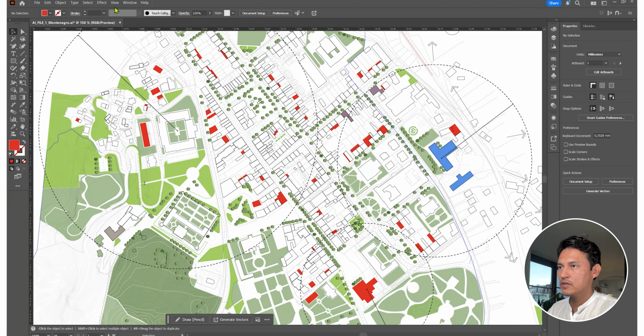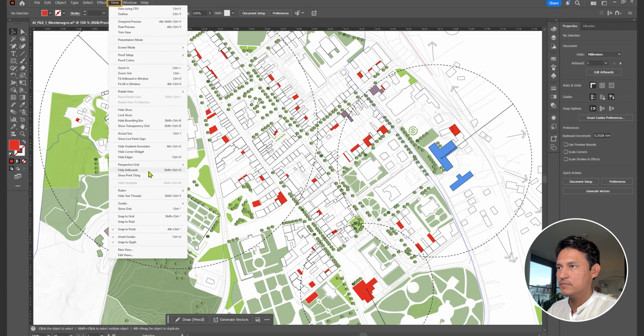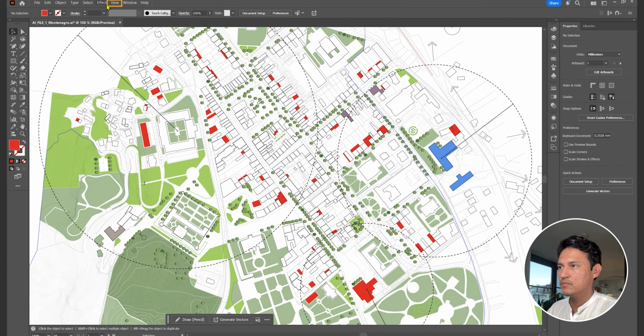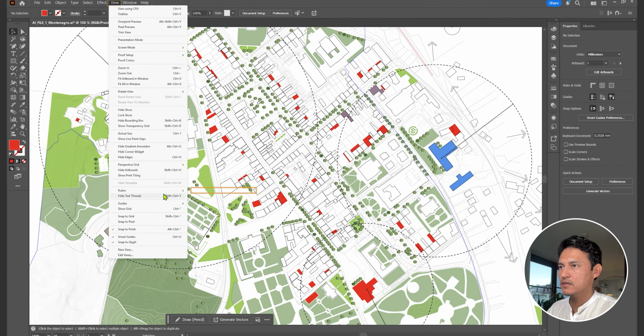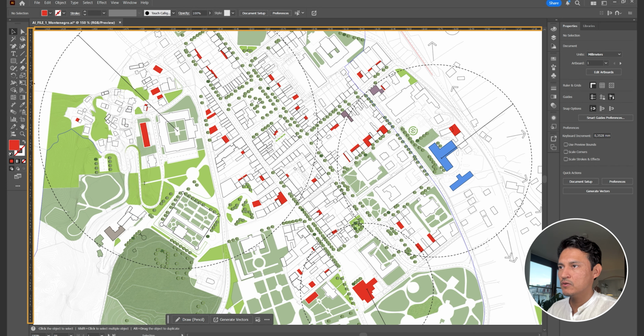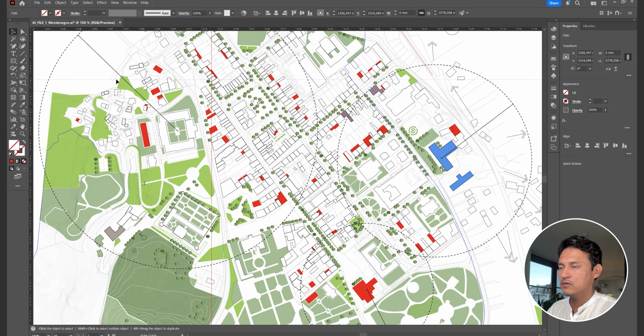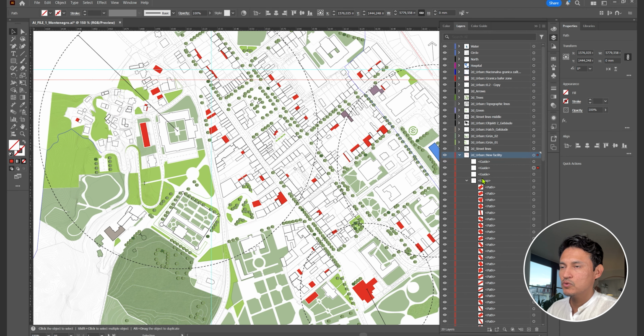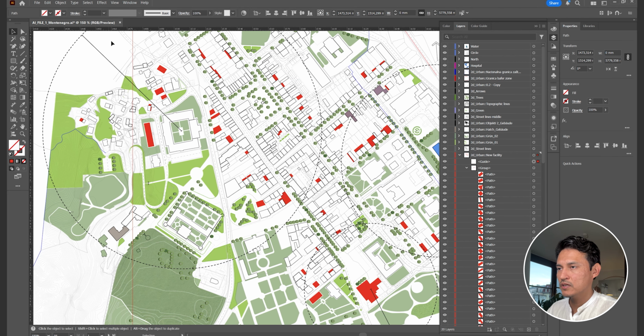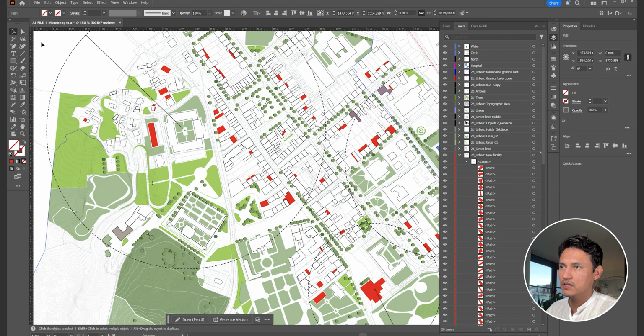A tool that I use a lot are the guides, but to see them first you have to activate the rulers. For that you have to go to the view menu, then select rulers, then you check show rulers, and now you see the rulers. And from then you can drag the vertical and horizontal guides. This will be saved in layers, so you can turn them on and off or delete them with the keyboard or by moving them to the ruler's position.